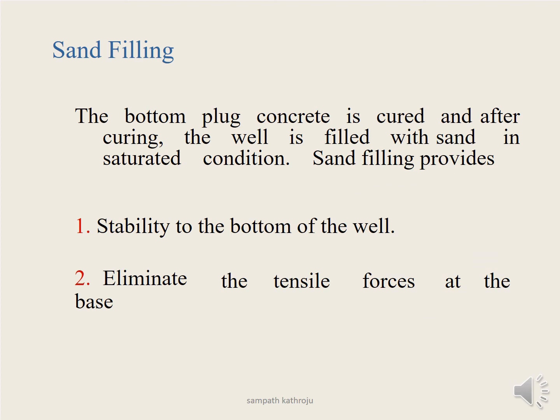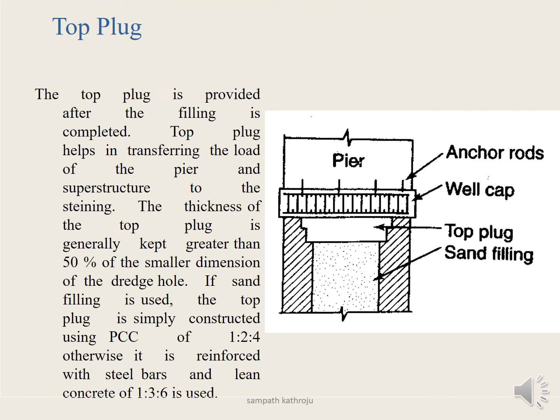Then the bottom plug is created, and it is cured. After curing, it is filled with sand. The well will be filled with sand in the saturated condition. It provides stability to the bottom of the well, and eliminates the tensile force at the top plug. As you see, this is the portion just after filling the sand.